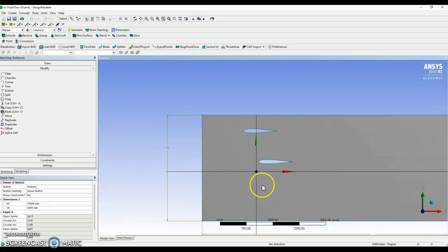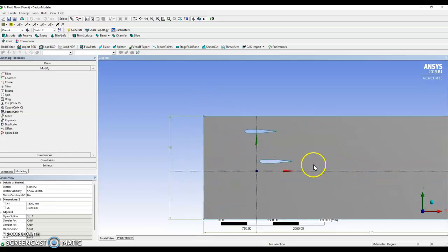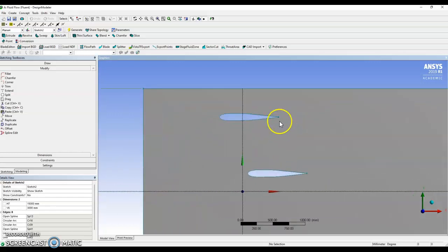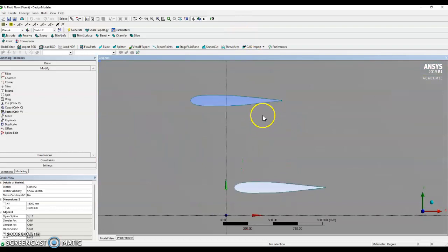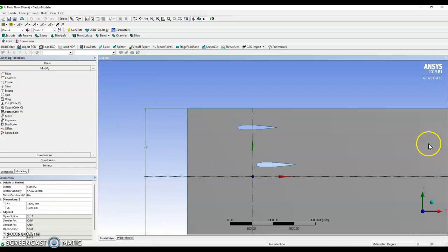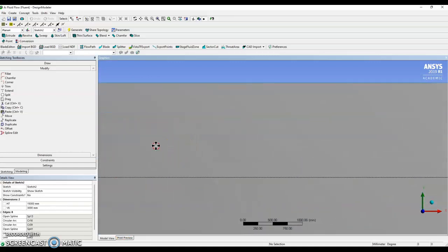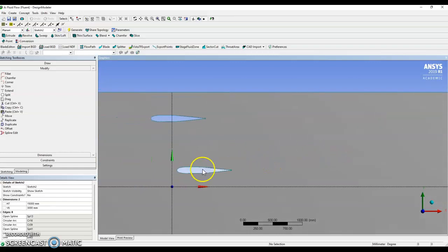and it would give you aerofoils in this configuration here. Then you would draw a box around it to simulate the environment, of course. Preferably, it has to be at least 10 times the chord of the aircraft, which has been done as part of my report. And then I like to use a ratio of 1 to 5, so it's quite long, but this would very well represent any turbulent air coming off of the back of this aerofoil.